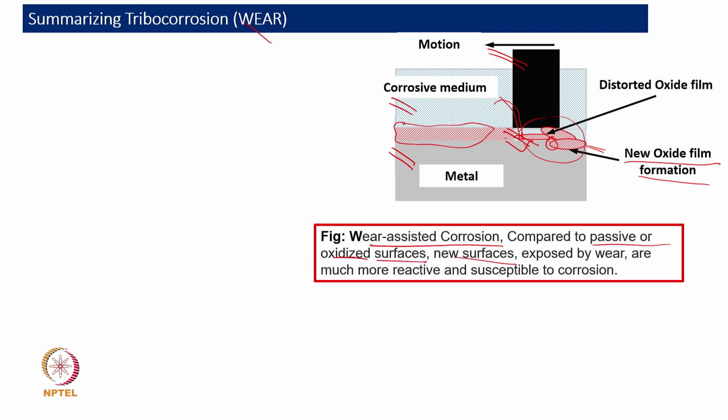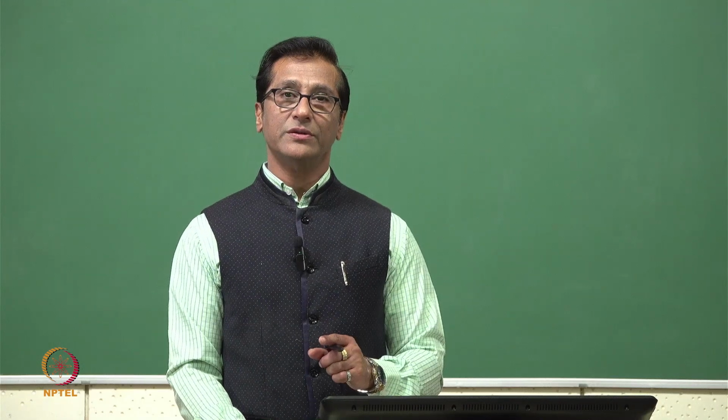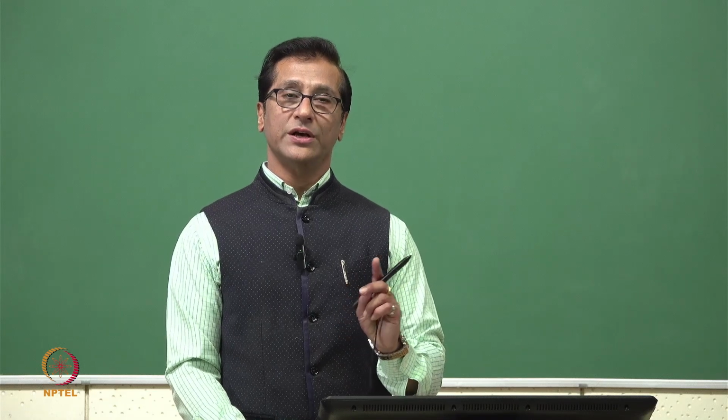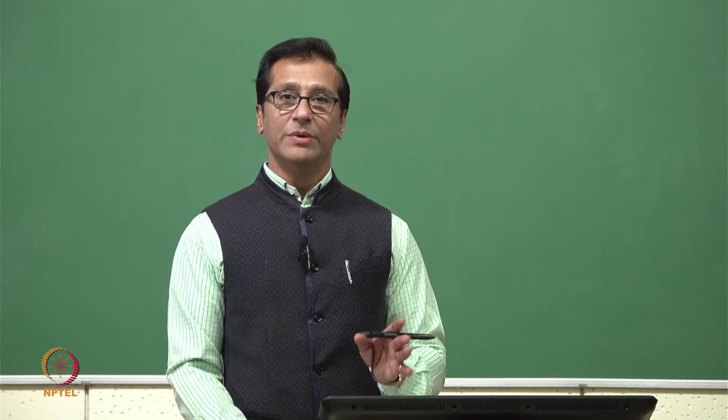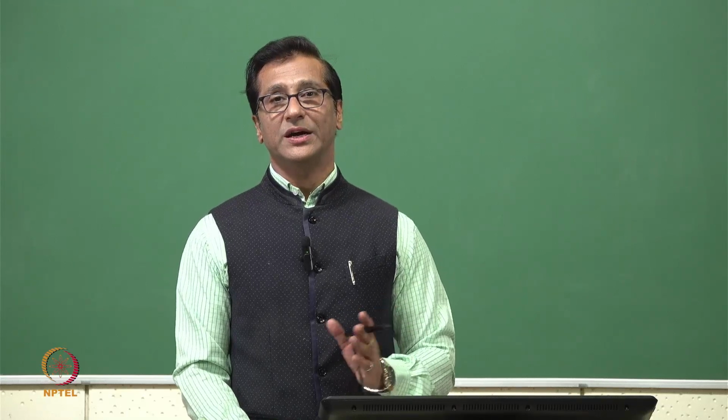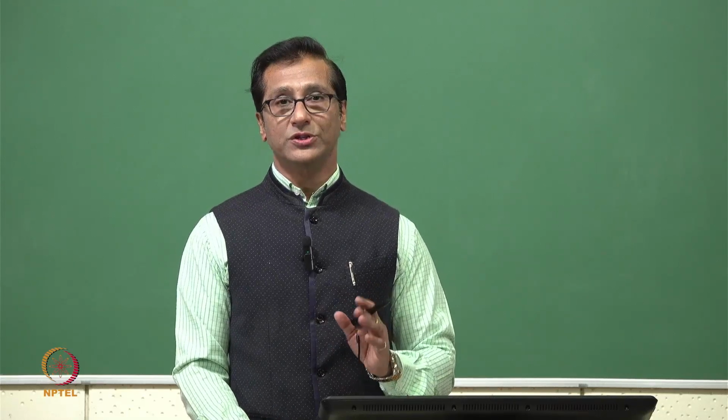New surfaces, which may be virgin surfaces, get exposed to the corrosive media, and they are much more reactive and susceptible to corrosion. So here, because of the wear, the surface gets exposed to the corrosive media. However, there was an oxide layer as prevention; the corrosive media was not supposed to do anything to it. But because of the wear, the surface gets exposed to the corrosive media. Corrosive media forms a layer, changes the clearance, and reduces the load carrying capacity. Again, the wear rate increases. So this is the word synergy we are talking about, and the two really help each other.